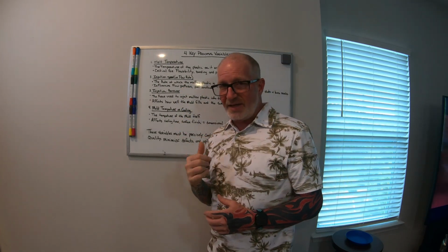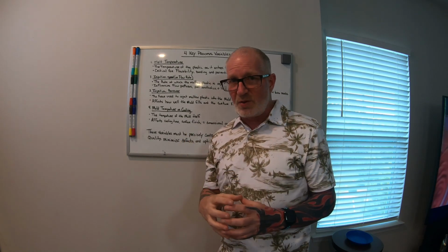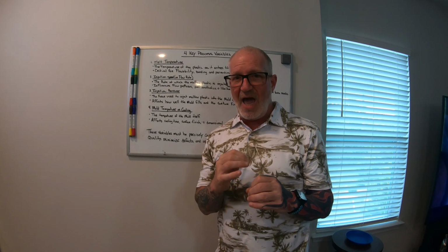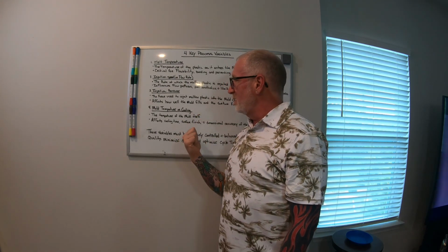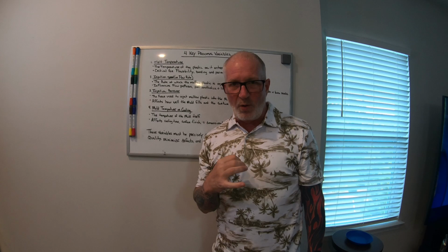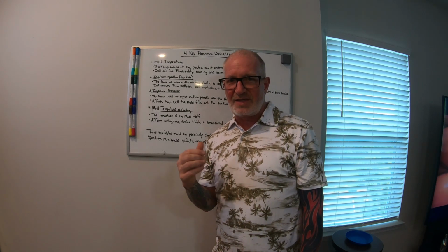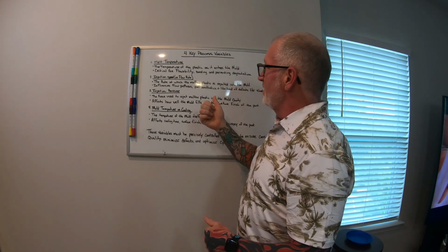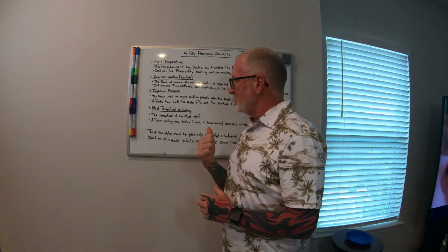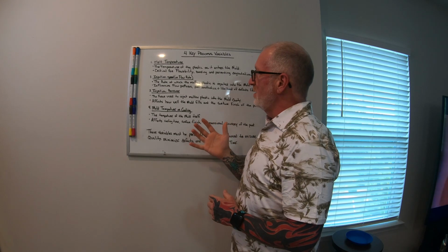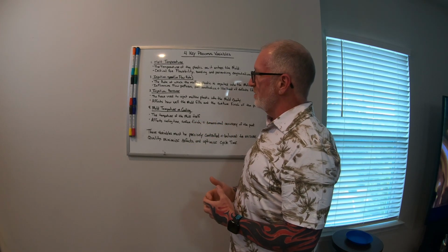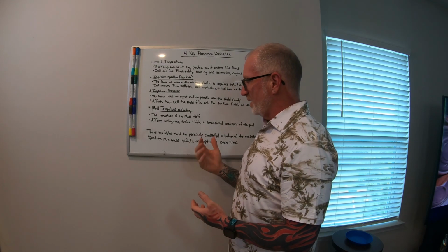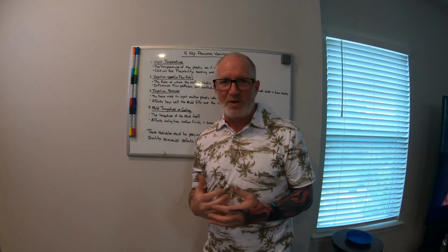These are some of the things that I do whenever I get a brand new tool in. This is some of the things I try. I might not be 100% accurate on what I'm saying here, but being in the molding industry as long as I have, this is kind of a standard staple of what I go by when I say the 4 key process variables. So I always go by melt temperature, speed or flow rate, pressure, and then cooling. That's what I always go by.